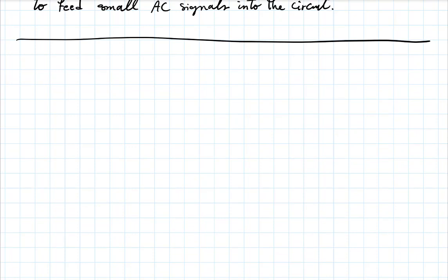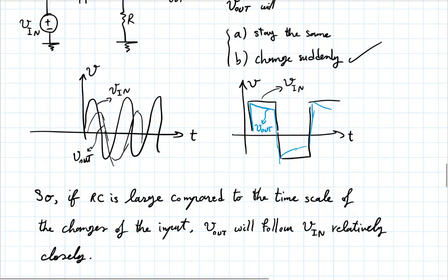No, it absolutely resists change in voltage. That's what the capacitor is doing. So why did we say the voltage, the set change at the end? The capacitor resists change in the voltage across the two plates, right? So one side will follow the other. The capacitor does not resist the change in one node voltage. It resists the change in the voltage difference. So if the difference doesn't change, means, yeah, absolutely, that's exactly what it is. It resists the change in its own voltage, right, which is the drop between the two sides. That's exactly correct. That's a very good question.